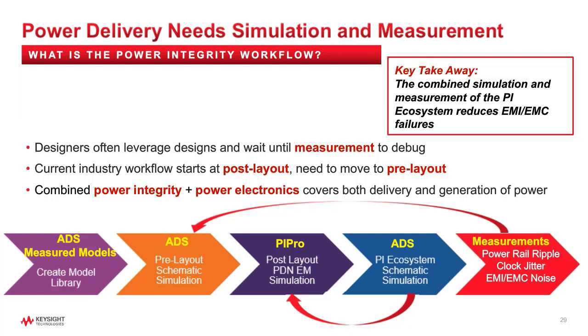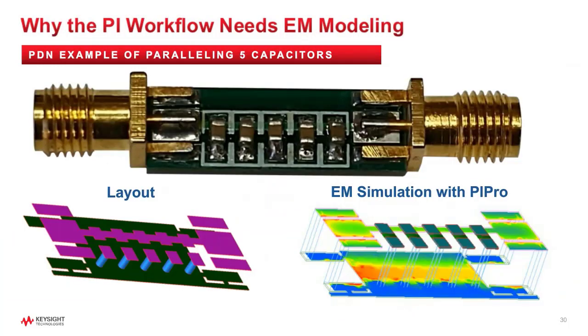Starting at post-layout EM often leads to the optimization of a bad design. It is better to start with pre-layout to get to the right design space before going to layout. Combining simulation tools for power integrity and power electronics covers the whole power integrity ecosystem from generation to delivery at the load and allows the designer to go through the complete design flow to avoid late in the design cycle failures. An example of why the power integrity workflow needs EM simulation is shown here.